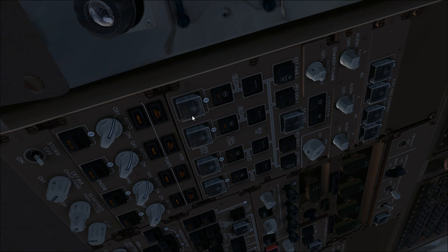In this case we have the off lights on and the drive lights on, just because the generator is now not online, because the aircraft waits to have a proper N1 rotation to set up the generator and put it online, and just because the engines are off, it does not sense any speed on the generator itself. At this point, as I said, generator control switch is on and checked, and the drive lights are checked. Now we shall turn on the APU.